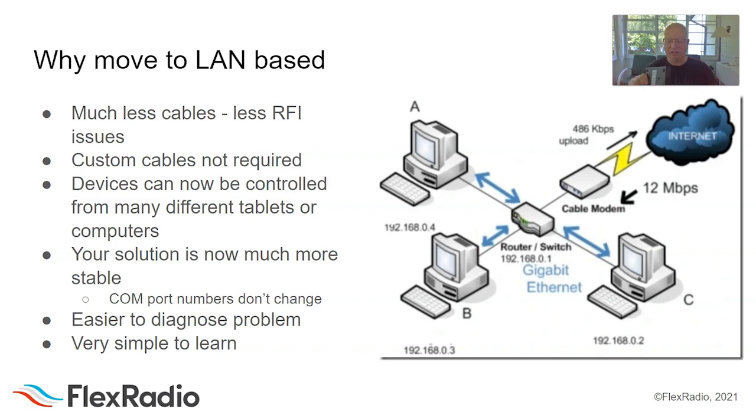And this is an 8-port switch by Netgear. Very popular. I like looking for these in metal cases. These work really well. And don't always get the cheapest one. While they all work, they all don't work as well as others. So, a good quality network switch. I look for the home business models or the prosumer models. And I often put, by the way, because this has a switching power supply on it, you can tell switching power supplies are really light, I tend to put chokes on them. This one I haven't done yet, but mix 31 or mix 43 chokes.